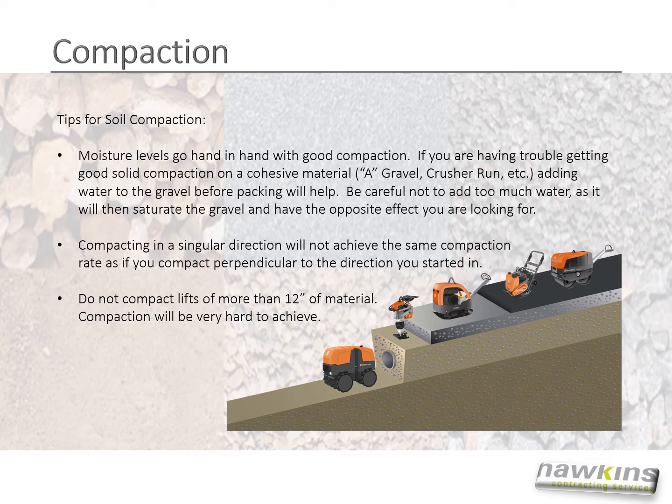you are looking for. Compacting in a singular direction will not achieve the same compaction rate as if you compact perpendicular to the direction you started in. Do not compact lifts of more than 12 inches of material. Compaction will be very hard to achieve.